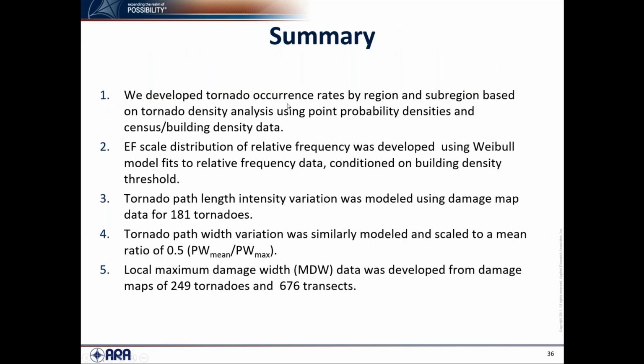So in summary, we developed the tornado occurrence rates by region and subregion to be able to develop corrections for that. We studied path length, path width, and maximum damage width intensity for a large number of different tornadoes, again, to feed into these other models.